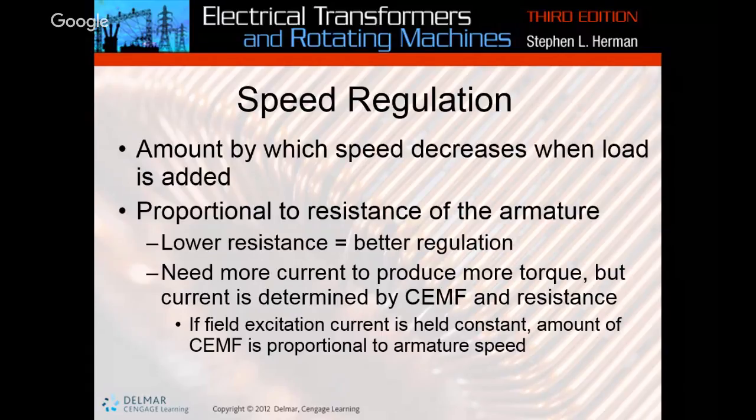Magnetic field. Good stuff. This reaction causes the armature to rotate. The rotating armature produces back EMF, which opposes the armature voltage and reduces the armature current. If the load of the motor is increased, the armature rotation slows and back EMF is reduced, since back EMF is proportional to speed.